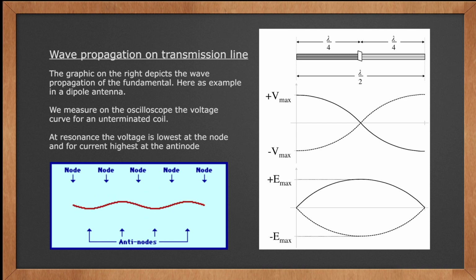I have not used much power. It's very far away, 5 centimeters away from the coil. The scatter experiment is supposed not to influence the coil at all, and we don't have much power here. However, if I really excite this one, and I use hundreds of volts and use directly a primary coil, at that point, and I have done that before in other tests, I burn the cable. The wire, and that was a thick wire, at a distance of 2 meters, did actually burn at specific points. And that's what you need to avoid. We can't have this.